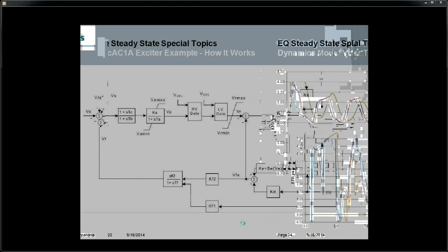You don't have to have a balanced three-phase transformer model. You can actually model the fact that it's an open delta with one transformer being larger than the other, and actually model that in specific detail. And you can also design and model single and two-phase circuits for overhead and underground installations.